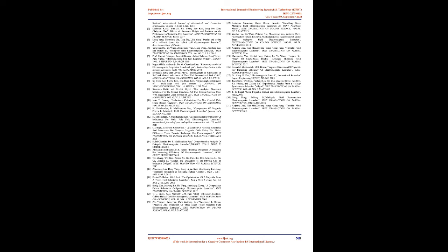5. Multipole field electromagnetic launcher. To propel an object or projectile in space with extremely high speed and in limited time, it requires huge repulsive force and long duration simultaneously. To achieve this, multipole field electromagnetic launchers are used. Multipole field electromagnetic launchers have a big caliber and a multistage structure in which multipole acceleration coils in one stage are charged simultaneously by a capacitor bank.